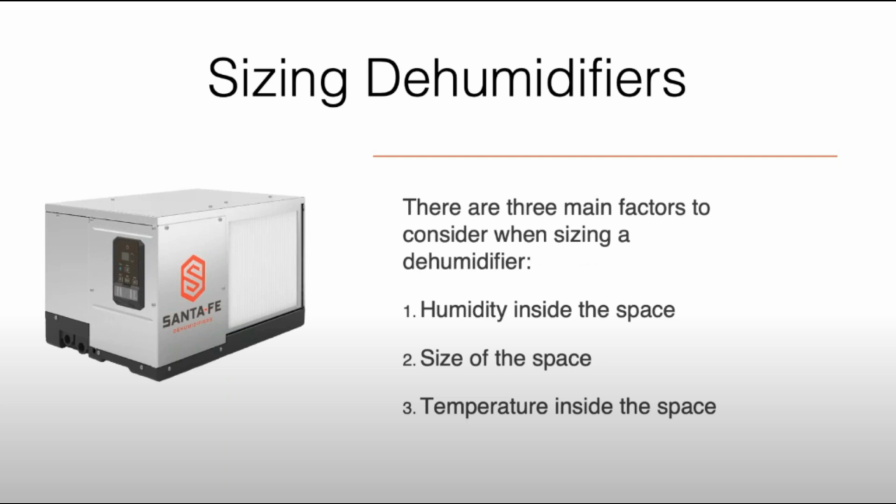There's a lot of articles out there about how easy it is to oversize a dehumidifier. And that's just not the case. When you set a dehumidifier to a specific RH, it's only going to run until it gets there. There's no concern of drying out a crawl space too much.